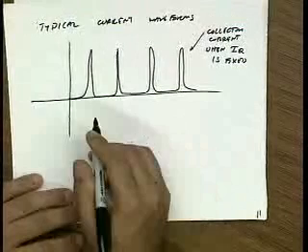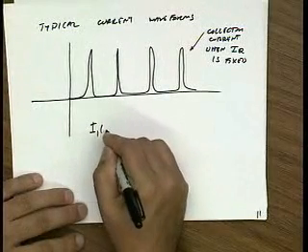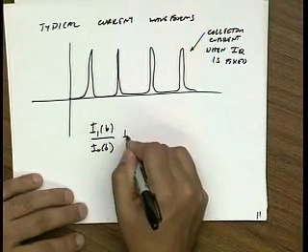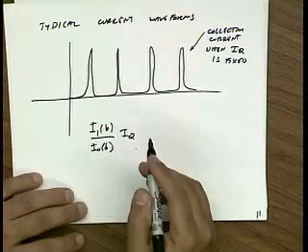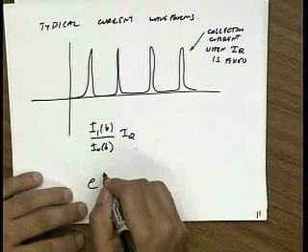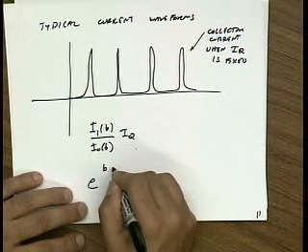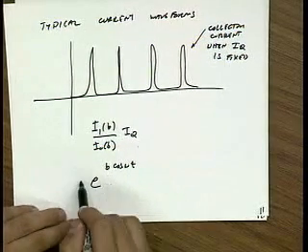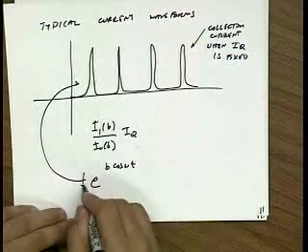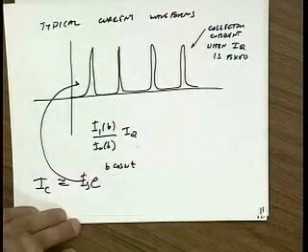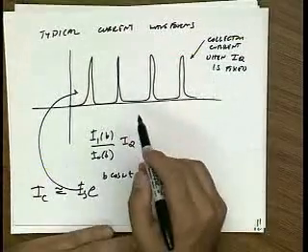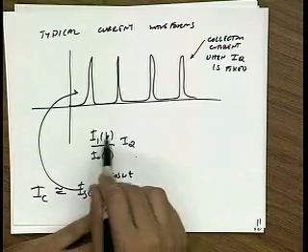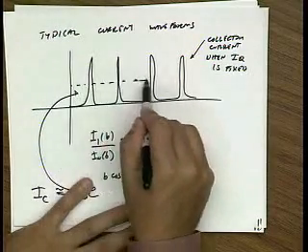In fact, go into Mathematica and plot I1, I0B, IQ, and actually it's easier just to plot B cosine omega t and make B very large. And this is what the collector current looks like. It's becoming very bursty, and so if you plot it for large B versus if you plot it for the bias current being limited, you get different waveforms, okay?